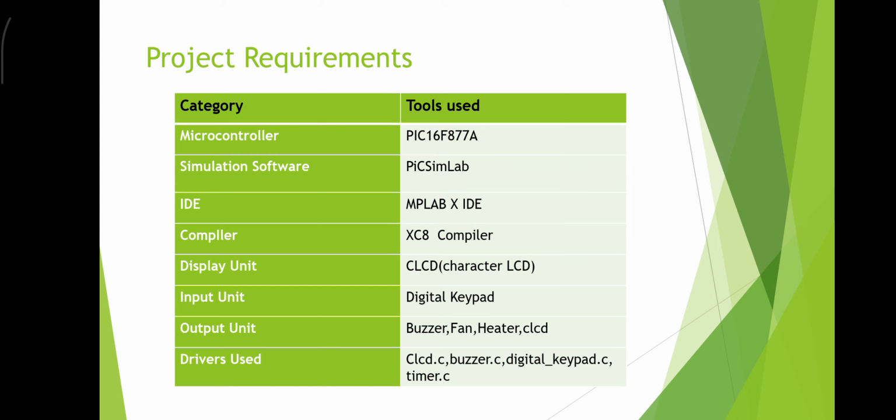Project requirements. In our project, we use both software tools and virtual hardware components. The heart of the system is the PIC16F877A microcontroller. We used MPLAB X IDE to write the code and the XC8 compiler to generate a hex file, and PICsimLab to simulate the washing machine behavior.